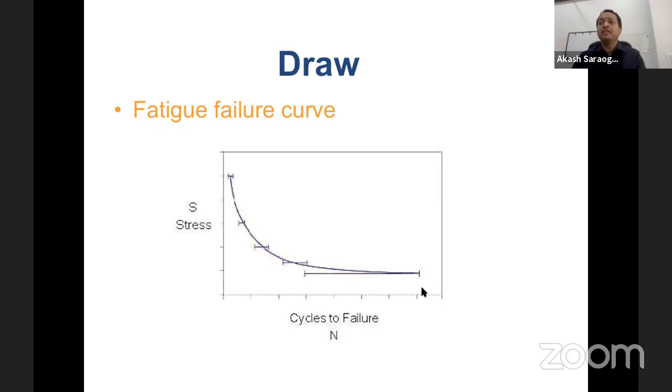So any material we make for arthroplasty, we need an endurance limit of minimum 10 million cycles. 10 million cycles is roughly equivalent to 10 years, which means that any material which we use for hip or knee replacement, we want that material characteristic to last a minimum of 10 years. That is what the endurance limit means.